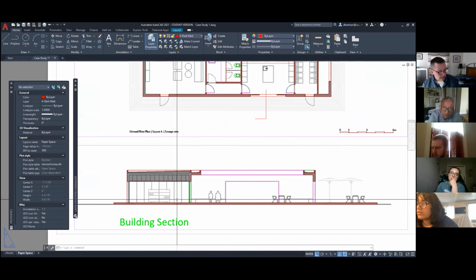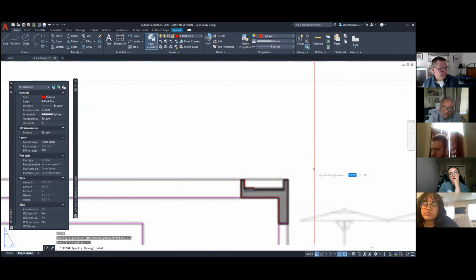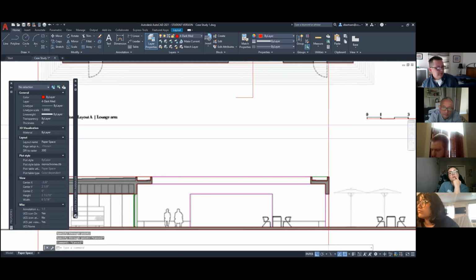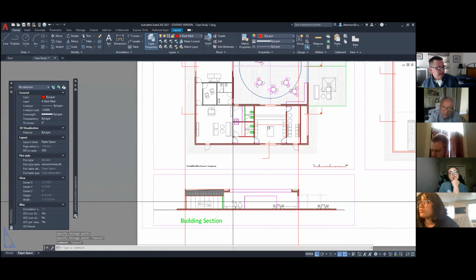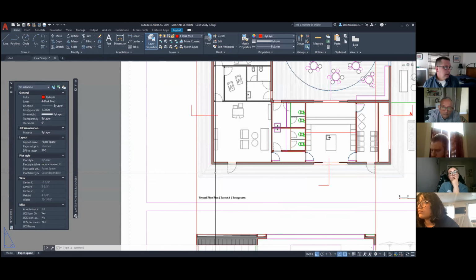So I'm gonna get back to my X lines, XL, enter, V, enter. And for our purposes, you could do this by eye, but this is how you would really do it. So now I have my section located, right hand, left hand, and I'm gonna move it by eye, really.